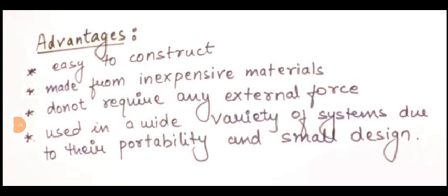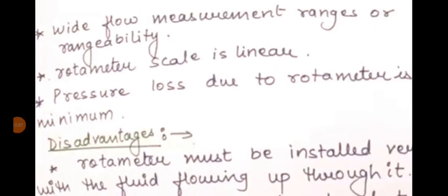The float moves in the upward direction due to buoyancy against gravity. So we are not using any external source and do not require any external force. It is used in a wide variety of systems due to its portability and small design. So these are the advantages of the rotameter.